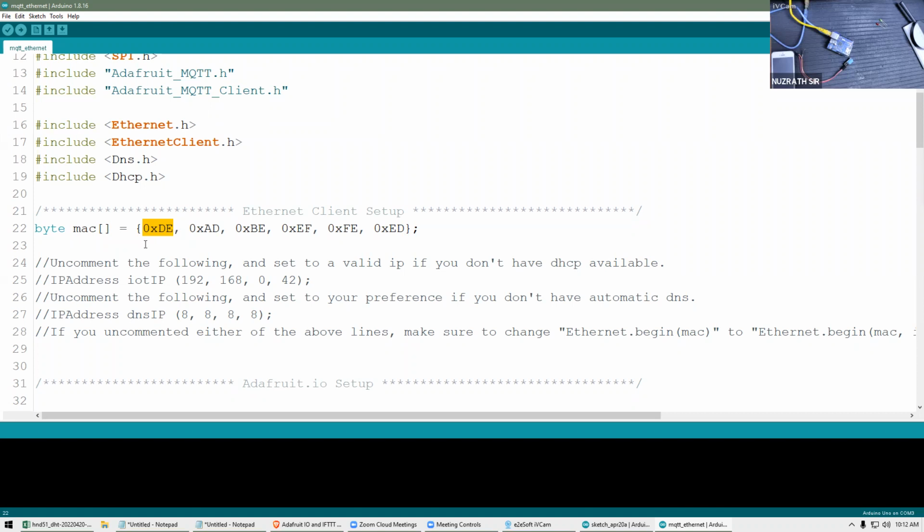That is the MAC address. If I take another Ethernet shield, the same example will come, child. So let's say we are doing practicals in the lab tomorrow. I give you 3 Ethernet shields, and you open the same file example. All of your MAC addresses will look the same. We will run and see whether our DHCP server can dynamically give us the IPs, and it can work without a problem. If there are any conflicts, we will try to manually update these MAC addresses.